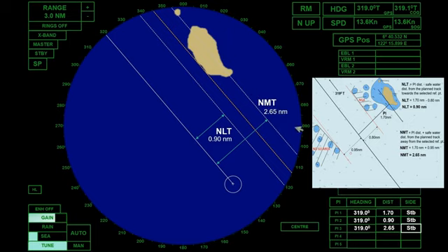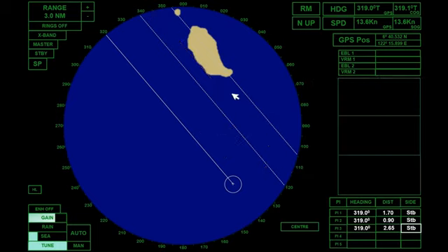Do not be confused about the set PI line on the radar, and the drawn lines on both sides of the planned track. Those lines are drawn in order to establish the not less than and not more than PI lines. If you want to set the PI lines in your ECDIS, it should be the same as the set PI lines in the radar. Let us take out this PI line along the reference point.